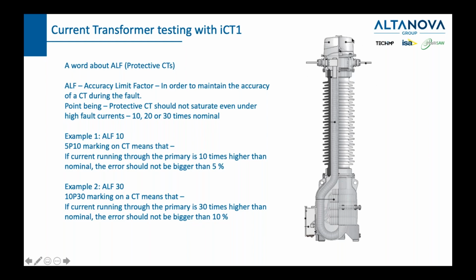That is quite important, because sometimes we forget that the CT is actually functioning in an environment where you have a primary side, the secondary side, and then you have something connected to the secondary side. You have the wires, and then you have your relay, or maybe a few relays, and that's the burden. And the burden also very much dictates the behavior of your CT. That's why every CT comes with the maximum allowed burden. Thank you, Simone, for reminding me.